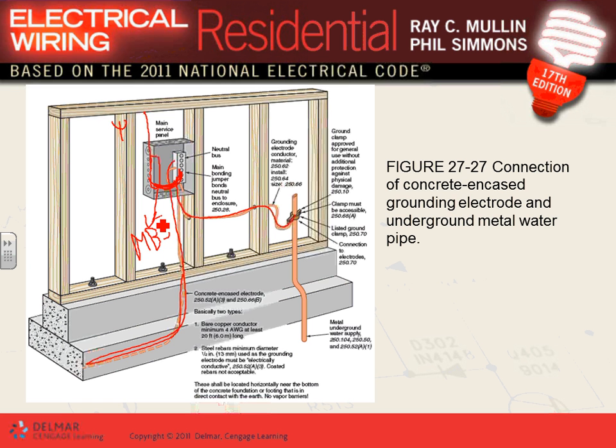By code, you need to tie to the water pipe coming into your building. Is this my metal underground water pipe? And you need to have concrete encased electrodes if you have concrete encased electrodes. The code requires you to have at least one grounding electrode means. You're going to hear the word grounding electrode. A grounding electrode is a fancy name for a metallic object in direct contact with Mother Earth.